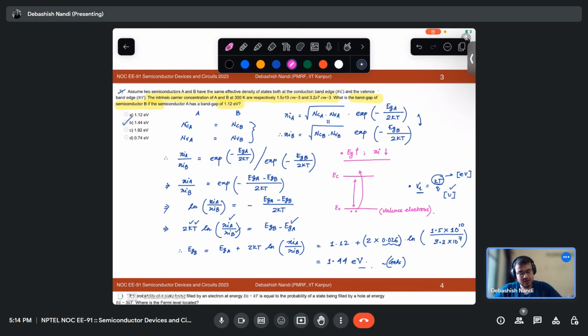Okay. So this electron, at a certain temperature, will get energized and become free. So as you increase the gap, more energy will be required, right? That's why for a particular temperature, if your EG is increased, then your NI will decrease. Okay, and the relation is very strong. It is exponential. See, this is minus of this. Okay, so I think you got the crux of this problem, and you can solve similar problems if asked in the exam.